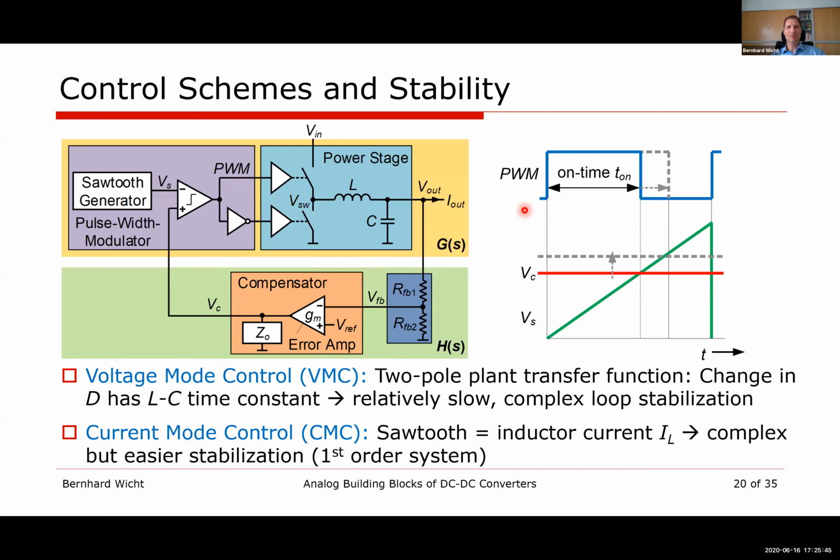I don't know if you benefit from FinFET technology or something like that. Of course, that's the limitation of switch mode conversion. The output is buffered by a capacitor. The capacitor has an ESR as well, right? This is not just a capacitor. There's also a parasitic resistance, and that always causes a ripple. So whatever you do, even if this capacitor gets really large, you still have some ripple, and nobody wants to have a large capacitor, but that's the way it is.